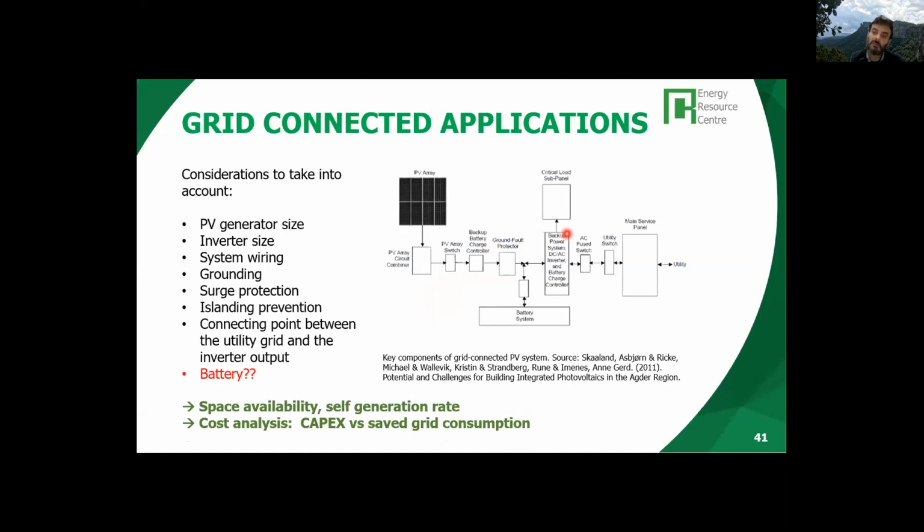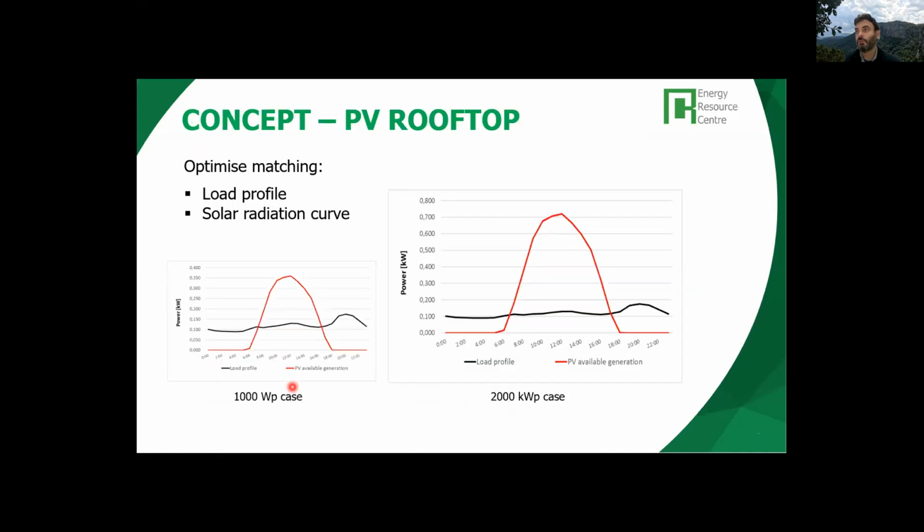How much our system is going to cost, what kind of savings in grid consumption we can have, for instance, if it is a grid connected system. Because the cost analysis might be a reason, if it's too high for our first design, we will need to revisit and redefine the PV system design, make it simpler or change something, because our first design was too expensive.